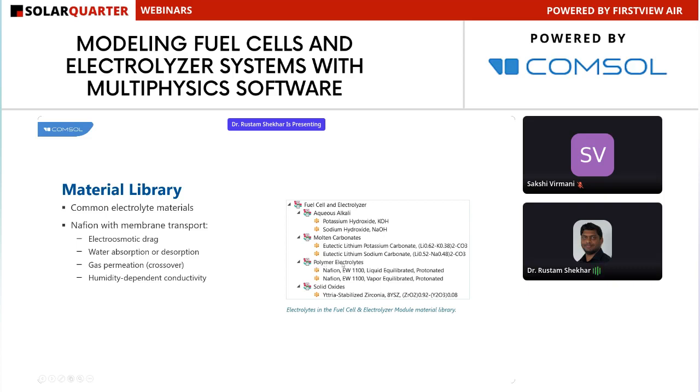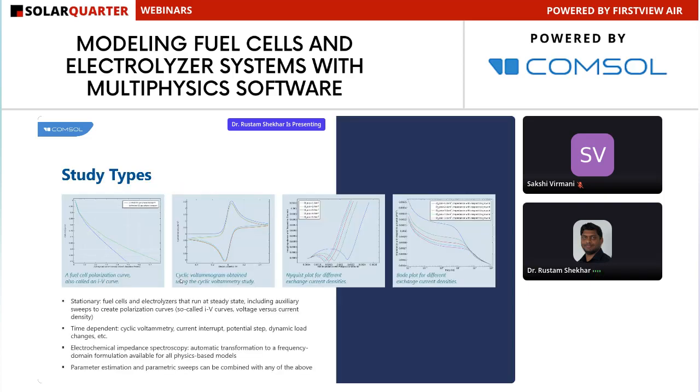For PEMFC, you have Nafion, which is liquid equilibrated or vapor equilibrated. And for SOFC, you have YSZ, which is the 8YSZ setup. So you can directly start using these for Nafion: electro-osmotic water drag, water absorption, gas permeation, and humidity-dependent conductivity, which is the most popular membrane available in fuel cells.